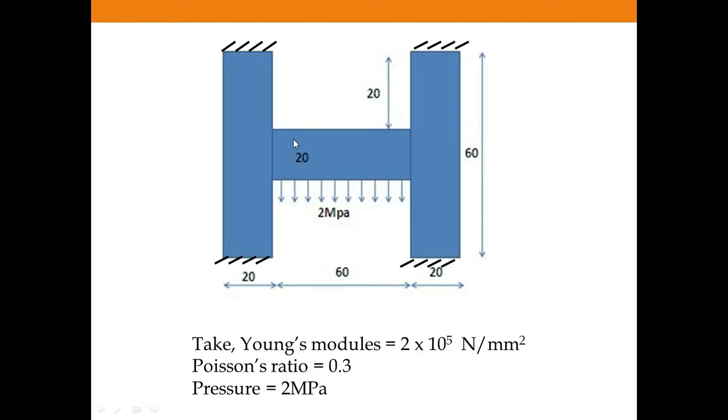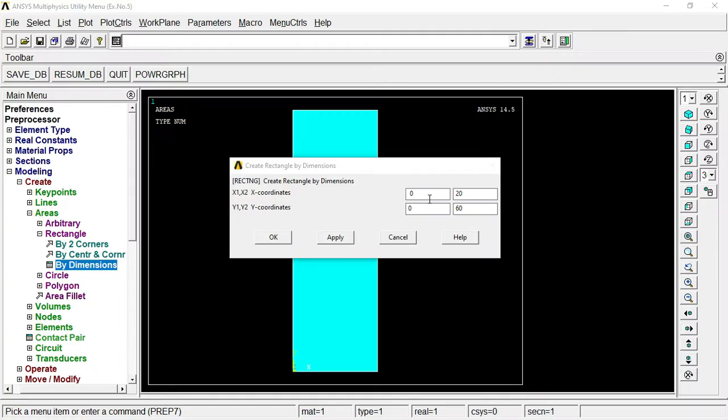In order to create the center area, enter x1 distance 20, x2 distance 80, y1 distance 20, y2 distance 40.